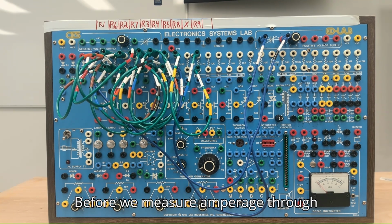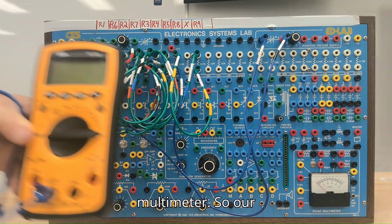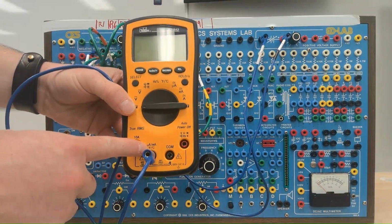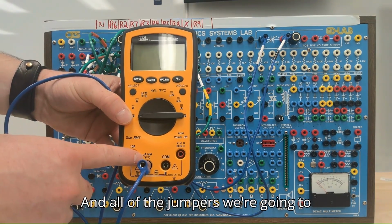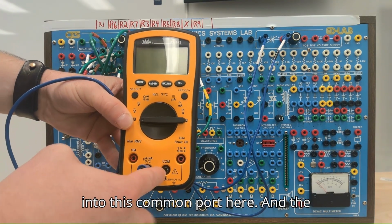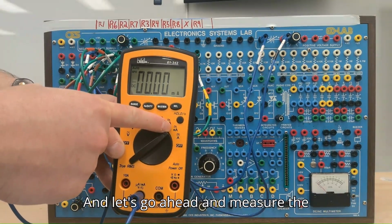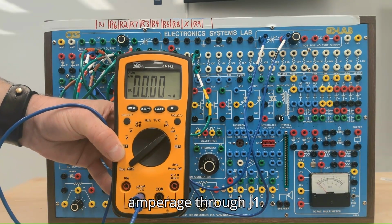Before we measure amperage through J1, let's do a quick overview of our multimeter. So our multimeter, we have our temporary test lead installed in the milliamps port of our meter, and all of the jumpers we were going to remove from our circuit will be installed into this common port here. And the setting our multimeter needs to be in is this milliamp setting here. And let's go ahead and measure the amperage through J1.